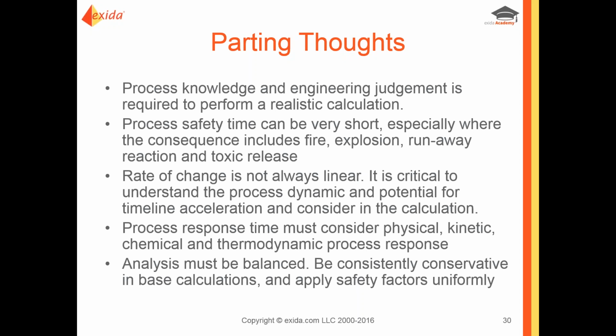And then, of course, the analysis must be balanced. I mentioned a couple times that instead of picking your base process safety time from the excursion, you could take it from the top of your normal operating envelope. If that's the case, you want your time to trip to be from that normal operating envelope as well. So when we apply the analysis, we want to be consistent in where we put the conservatism in, not double dip for that, and apply our safety factors uniformly. So that is what I had.